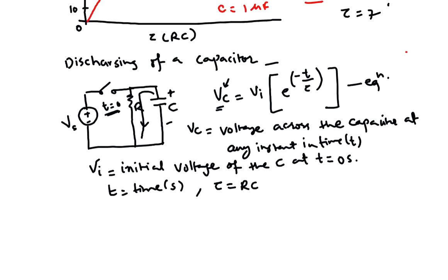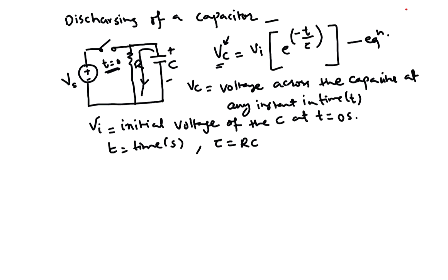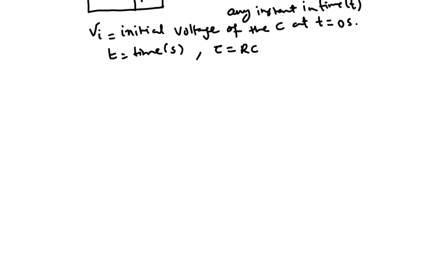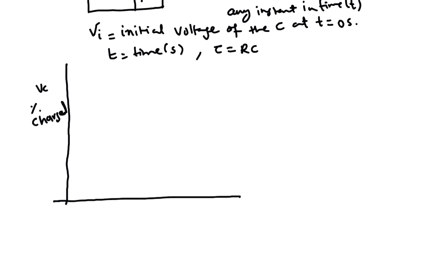So how about I now draw the curve describing the discharging behavior of the capacitor. Here it is. You again have this voltage VC, which is basically the percentage charge of the capacitor. Initially we are assuming the capacitor is fully charged, because we have seen how the capacitor got charged, and we say that now the capacitor is charged to its full value, 99.6% that we saw before.